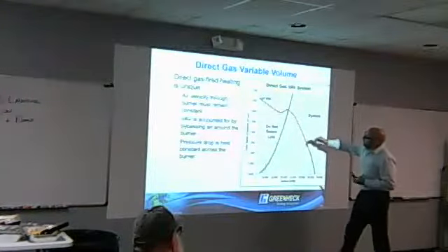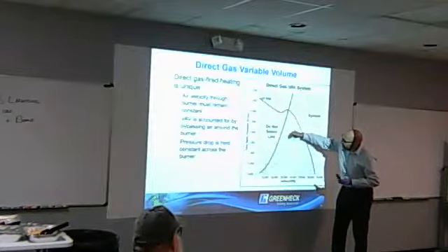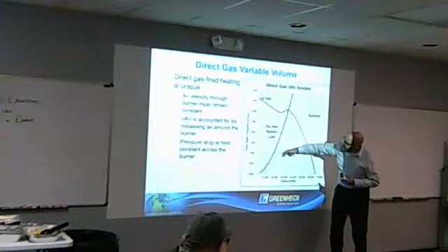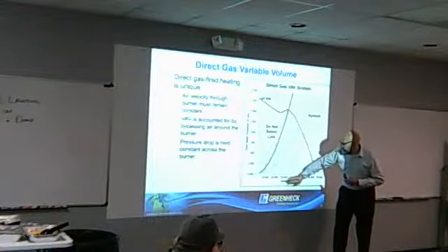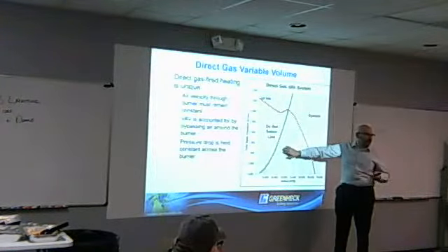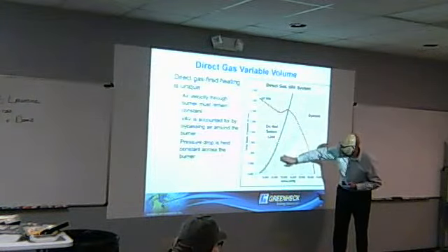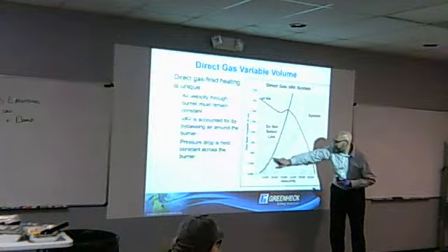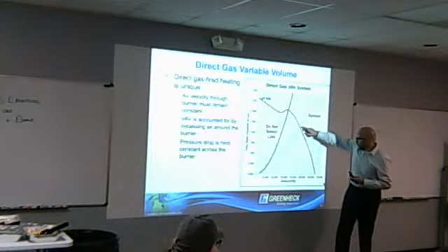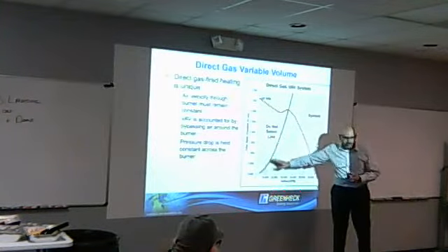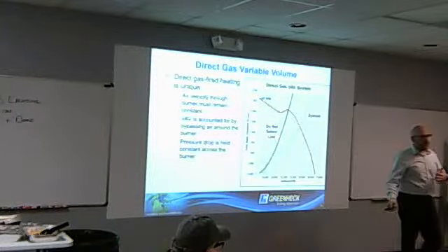If this was shifted for whatever reason, and let's say the line was over here, we'd say we can't go below 6,000 CFM because we're crossing the line. In this particular case, the line allows us to go to 16,000. So we could go from this point, call it 46,000, down to 16,000. That's pretty good in terms of variable volume.